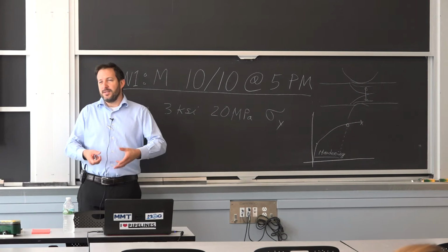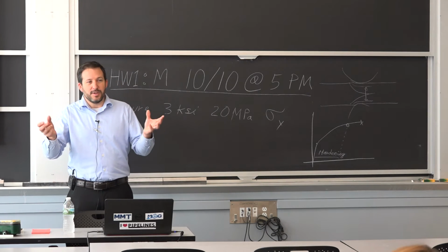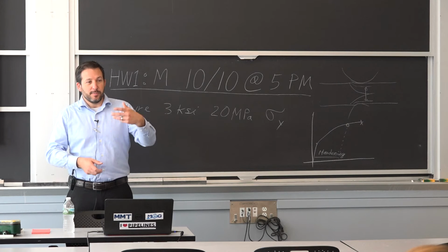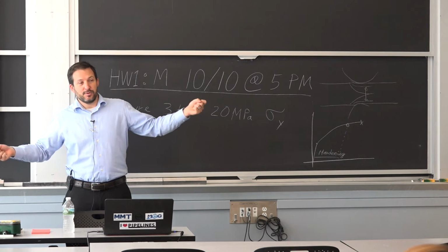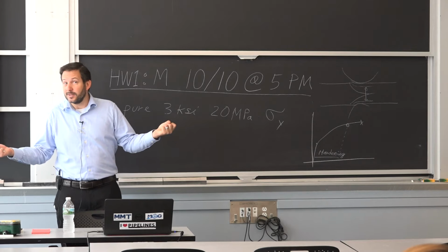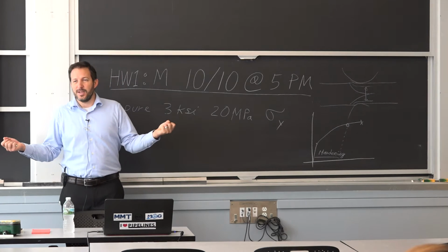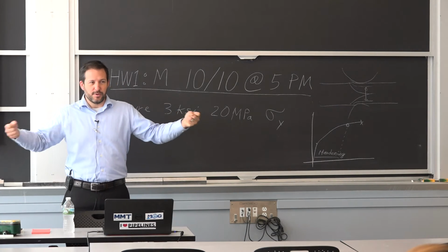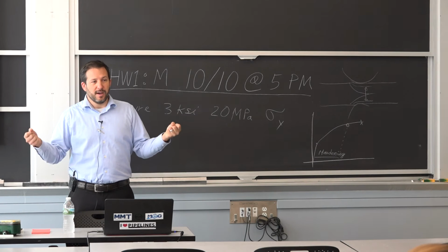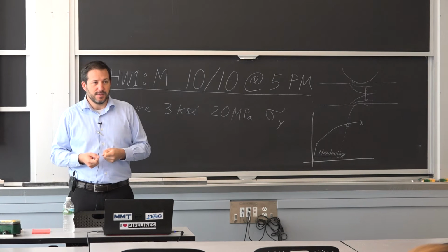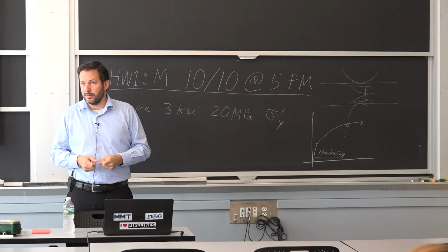Well, the concrete is never going to be able to deform anyway. So why would I put a wire in there that can stretch to 300% before it breaks? It doesn't make any sense. I'm wasting my time. So what I do is I stretch the wires as well. So for the amount of money I spend for the steel, it's 3 times stronger.